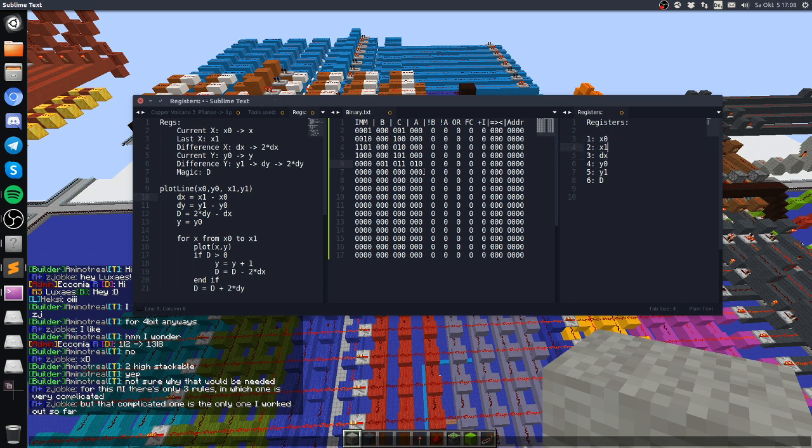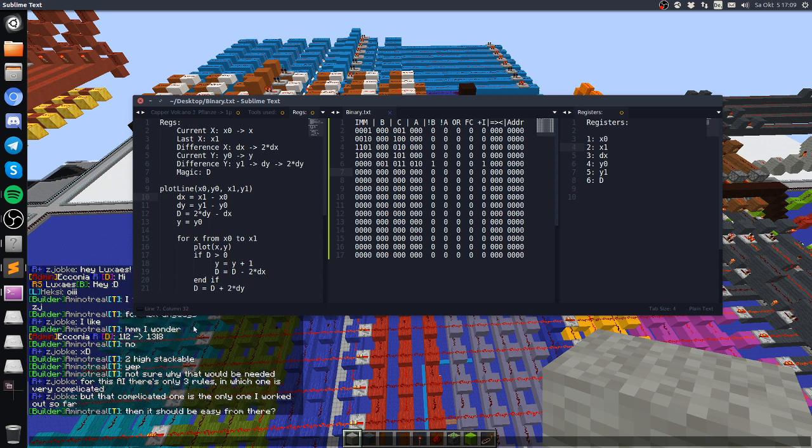If we want to subtract, x0 is 1. 1 is the negative one, so we're gonna make that one negative, and we add carry in, so that subtraction is active. So that's just doing subtraction. That one minus that one. That should result in something which is, wait, let me see, we had 1 and 13, so x1, which is that one, minus x0, and that is 12. So that should be 12.